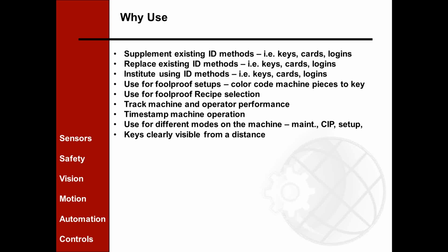You can track machine and operator performance. You can get timestamps for your machine for logging. You can send that up to a SQL database. You can log in on your HMI, you can log in on your PLC, you can even do trending, whatever. It can be used for different modes on the machine, so you can have like a maintenance mode or a clean in place or a setup or something like that. That would be potential uses for this also.